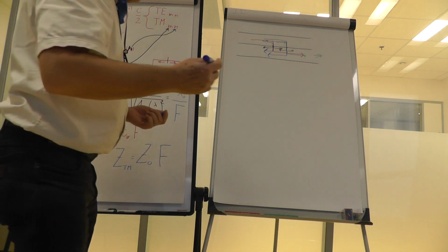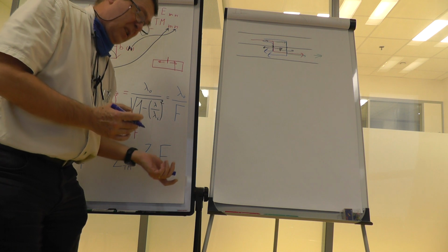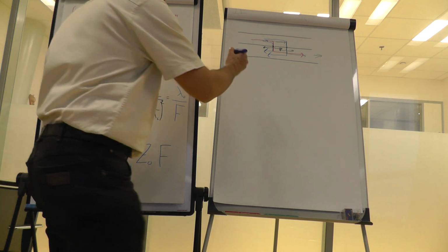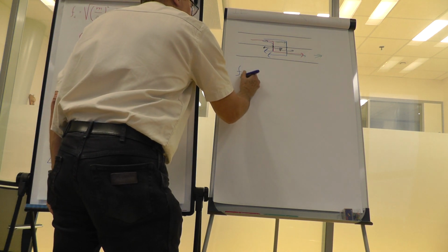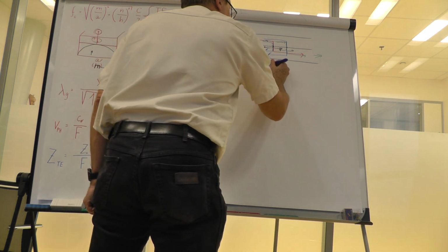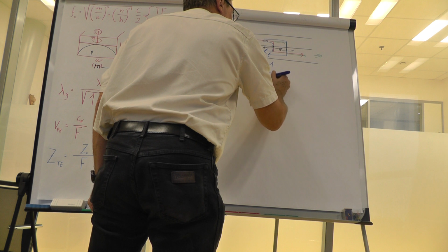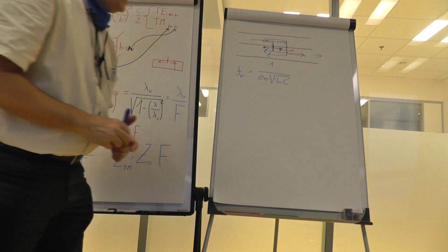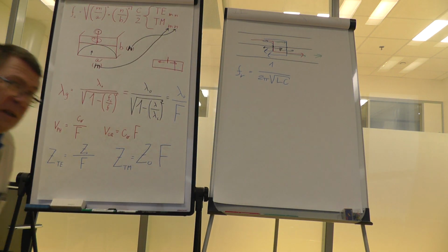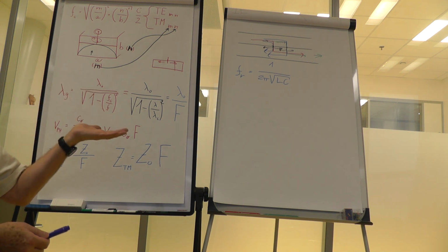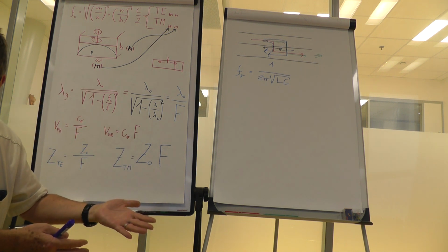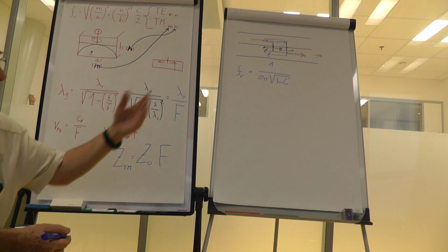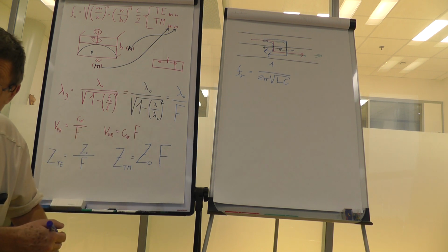You remember, if we have a resonance circuit constructed from an inductor and a capacitor, and both of them are ideal, then the resonant frequency given by the Thomson equation is 1 divided by 2 pi square root of L C, where L is the inductance and C is the capacitance. Now, this is quite a simple equation, so if you want to tune your circuit to some frequency, you can freely select inductor and capacitor as far as it satisfies the equation.